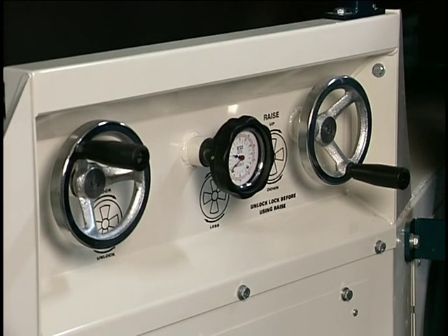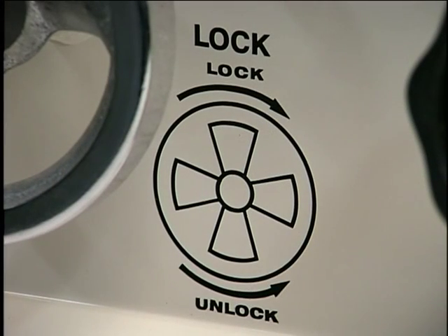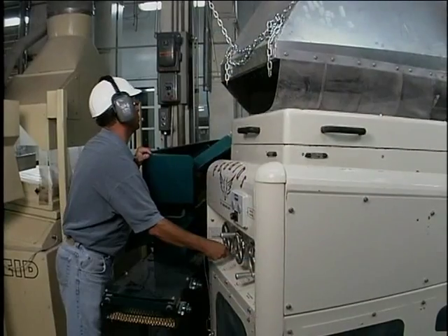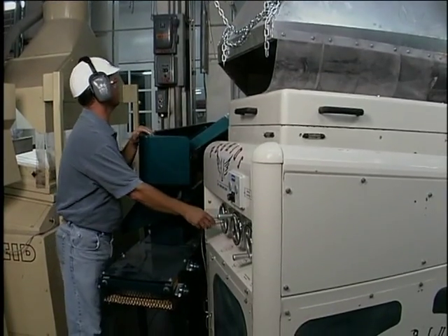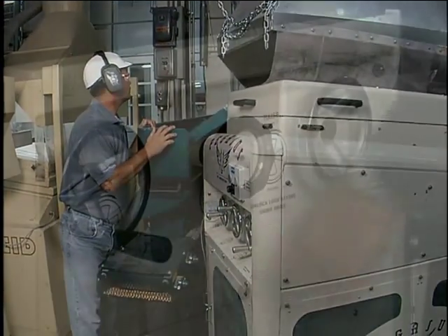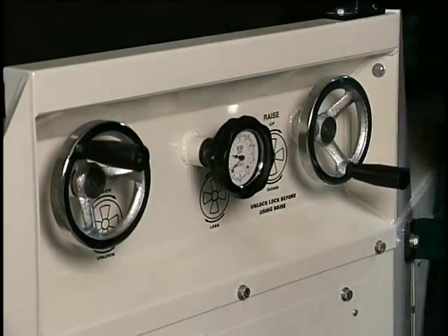Do not over-tighten the clamp. You will feel resistance when the clamp engages, and the hand wheel should snap backwards slightly when you let go. Please remember not to adjust the side slope without first unlocking the clamp, and always re-engage the clamp when adjustments have been completed.